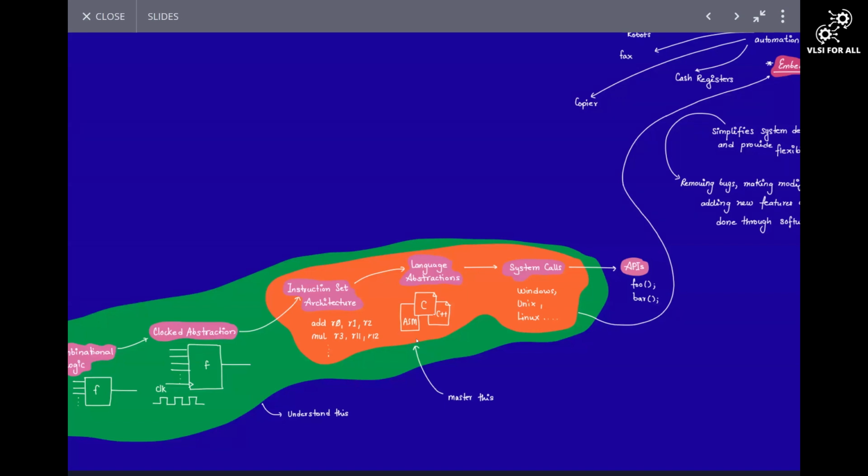So this smart bulb is not just a bulb. It also has a Wi-Fi processor within it. It is basically connected to the cloud. So the current state of this smart bulb will be indicated to our app via the cloud using Wi-Fi. You will also connect the smart bulb to your Wi-Fi by passing the SSID and Wi-Fi password over that Android app. Once the smart bulb is connected to the cloud, let's say AWS or Azure, whatever is being used at the backend,